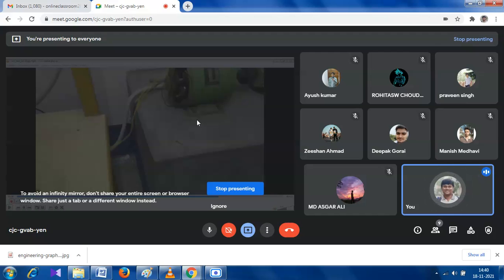All these data are written in the nameplate. So from the nameplate we can conclude that the maximum field current should be 0.28 for this experiment, for this machine. The value is written on the nameplate of that machine.